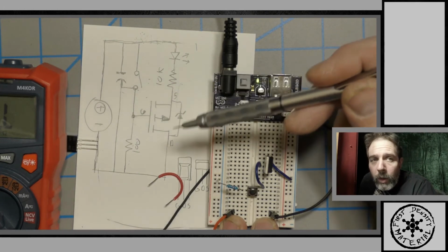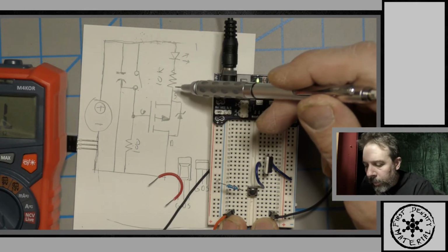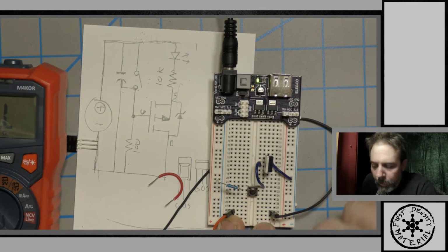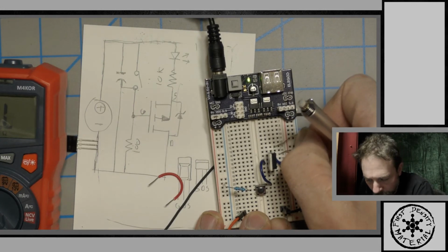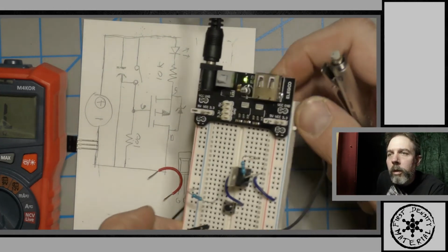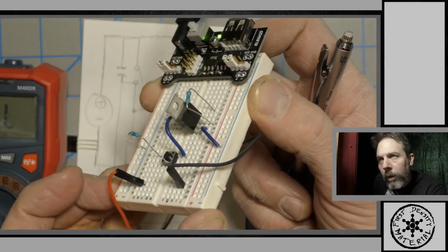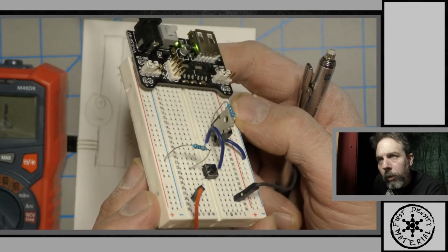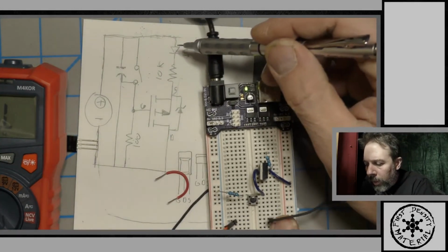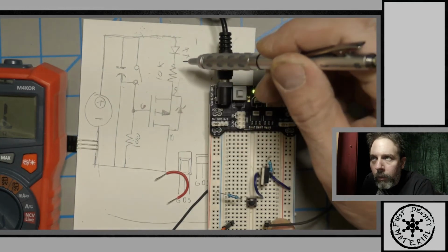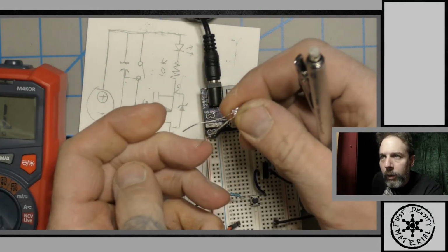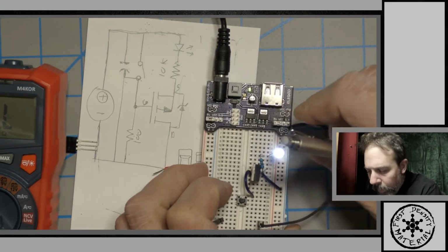Alright, let's handle the LED next. These are not in any order, it doesn't matter where you attack. I'm just attacking anywhere. So in this case, I have my source, that's the third pin on the MOSFET. And just so you have the view so far of it, in case I'm getting too fast for you, it looks like that. If you look, the LED's positive is hooked up straight to positive, and it's feeding the negative from the MOSFET. So the longer leg of the LED is hooked into the positive channel, and boom, it turns on.